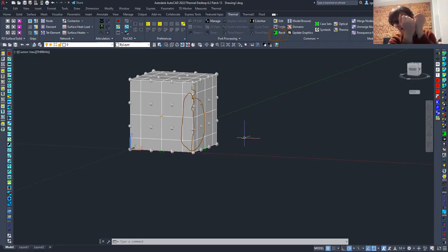So you have physical contact of two aluminum surfaces, but then you also have bolts going through them. And both of those are going to contribute to your heat transfer at that surface. So basically you would go through that same exercise. I don't know if we want to do it now, that might be a little too much, but you would go through that same exercise with each of these surfaces.